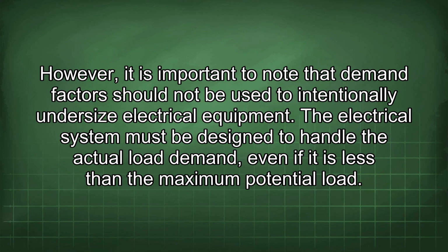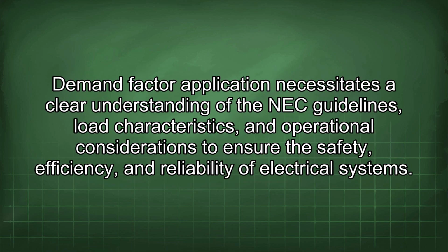However, it is important to note that demand factors should not be used to intentionally undersize electrical equipment. The electrical system must be designed to handle the actual load demand, even if it is less than the maximum potential load. Demand factor application necessitates a clear understanding of the NEC guidelines, load characteristics, and operational considerations to ensure the safety, efficiency, and reliability of electrical systems.